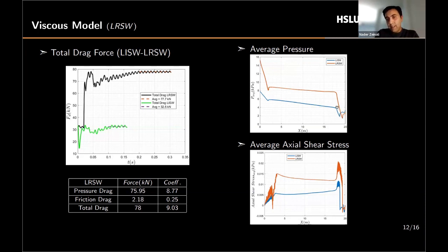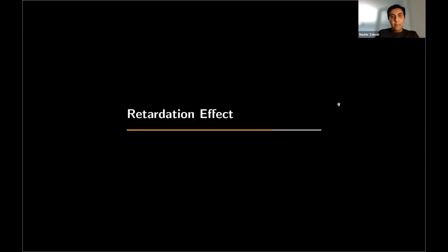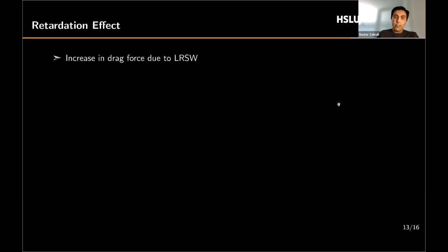By precisely locating it, you can find out that the large amount of pressure reduction is happening within the expansion waves. If you're looking to do something to decrease this pressure reduction, I think it should be within the expansion wave region.